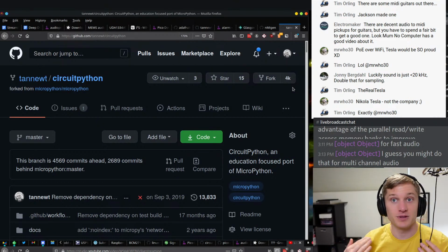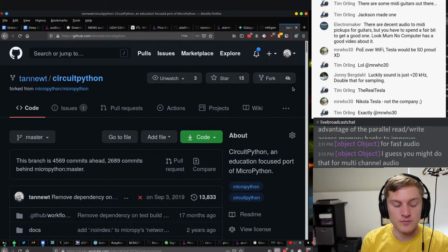Otherwise, you may actually be able to hear it as part of what you're listening to. There's some complicated math in the NRF52 side that tries to figure out the optimal version of that. But it has the challenge that the PWM on the NRF52 is running a lot slower than the one on the RP2040.